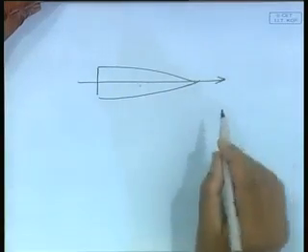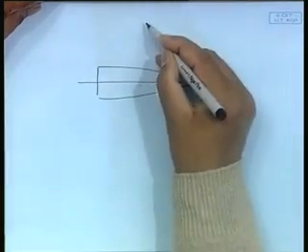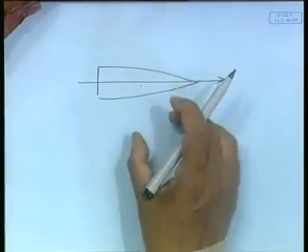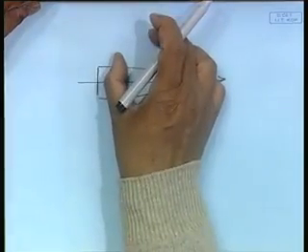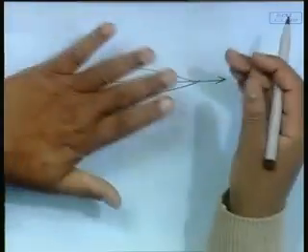Now the body is symmetric. So if I shift it this side, there is not going to be any motion this side. So my surge will not induce any motion in sway direction. So surge and sway are decoupled. Similarly, surge will not give me heave or trim. But we also know some modes are coupled. In particular, heave and pitch are very much coupled.